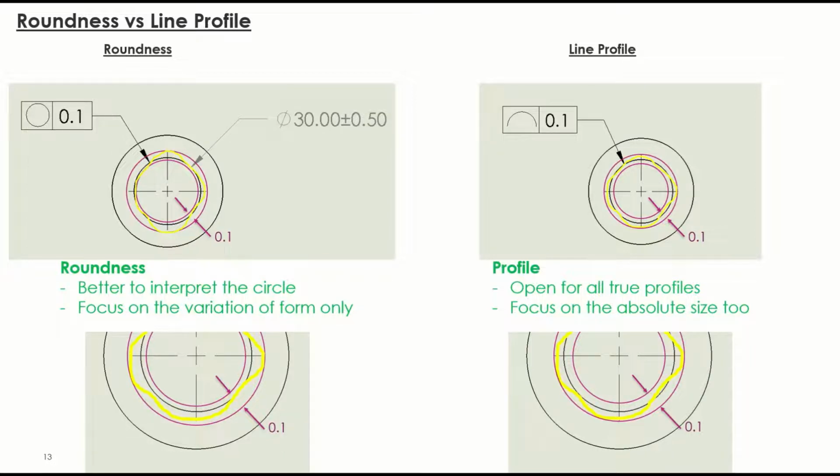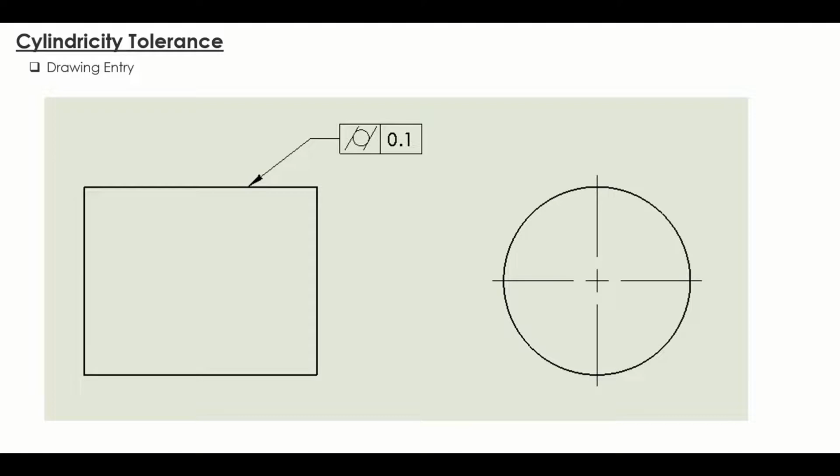That's all on roundness tolerance. Next, we will move to the last topic of form tolerance, cylindricity. Roundness tolerance controls the shape of circles at a single cross-section. The callout at a cross-section is independent from those in other cross-sections. If you want to control all cross-sections along the length of the cylinder, you need to choose cylindricity over roundness. Cylindricity is the 3D version of roundness tolerance and is the combination of straightness and roundness.